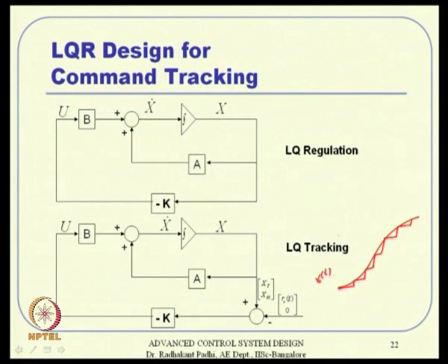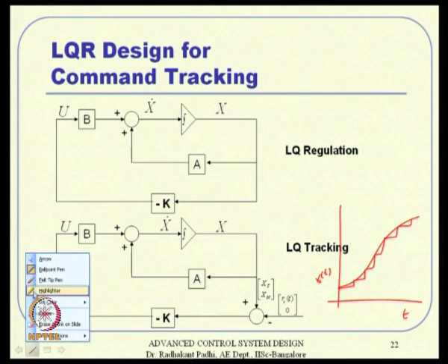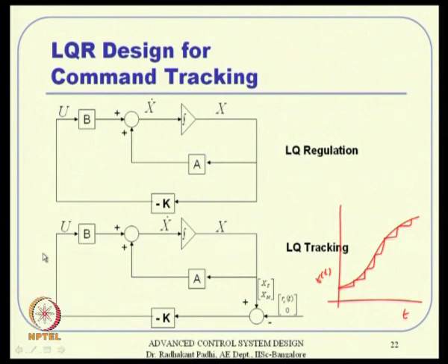Okay, this is rc and this is t. This is a normal assumption in tracking problems, what you call the quasi steady assumption. It is not really steady, but for every delta t it is assumed to be steady. Under that condition it can be shown that xt will go to rc, because xt minus rc will go to 0.